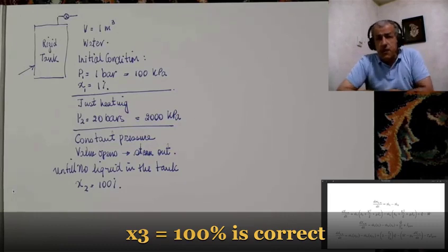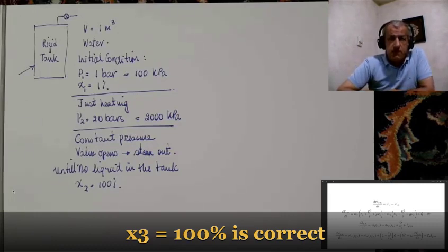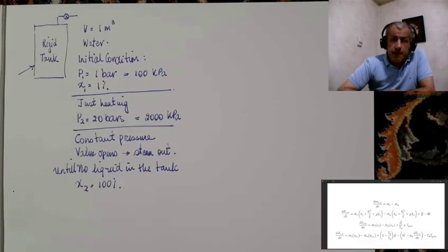This is similar to what you experience with a fuel canister that you use for your cooker or for a grill. The liquefied fuel in it is in a saturation state. When you open the valve, some vapor goes out of it, but the pressure and temperature remain constant.